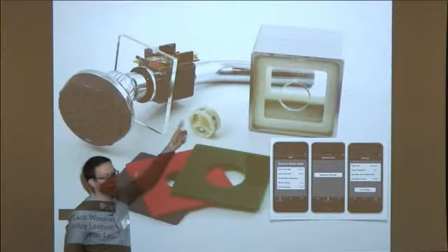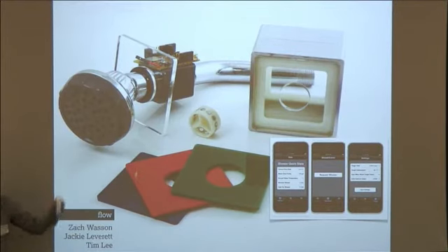They 3D printed this impeller that goes inside the tube. It has magnets on its periphery. Water rushes through, it spins up, and induces a current in a coil that's wrapped on the outside. That current is enough to fire up a microcontroller that uses Hall effect sensors to sense how fast the impeller is spinning, and then uses a low-energy radio to send that to a smartphone. This was first a class project at Berkeley, and then we had tech transfer across the bay to Stanford, where right now it's deployed in their dorms.